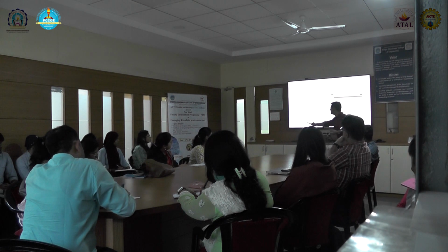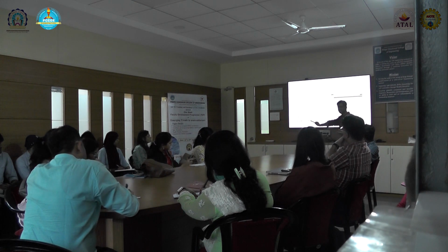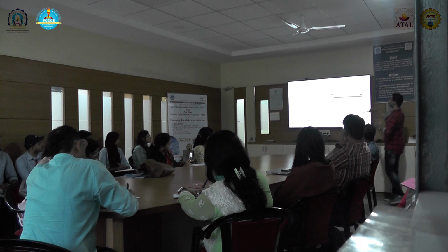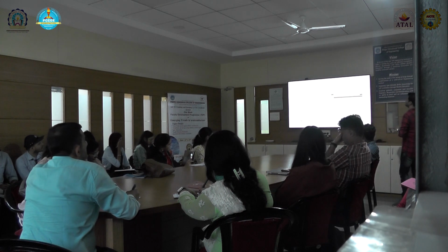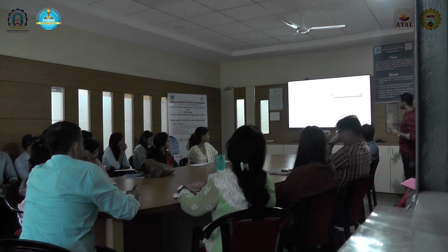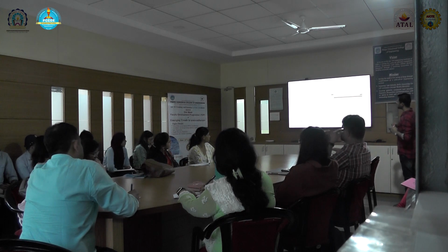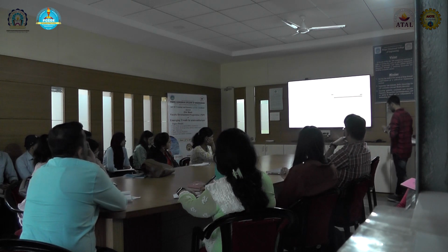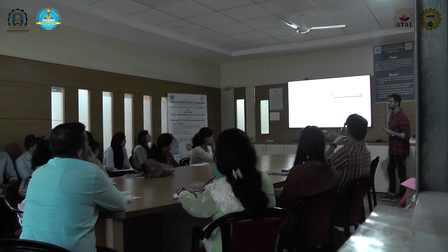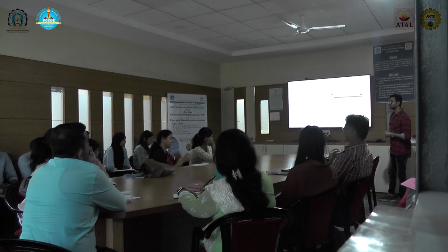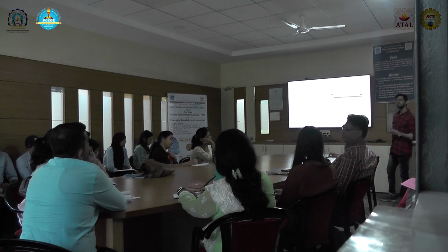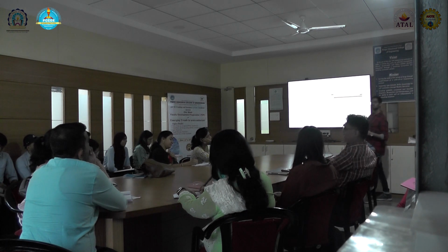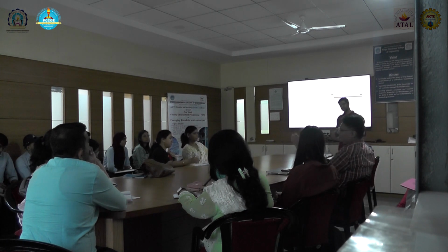If done 1 and done 2 are high in the same cycle, and then when you run formal on this, it will find a scenario where this is getting proven. Cover properties, unlike assertions, don't try to fail. They will try to show you a scenario where these three signals are high. So cover is like, in the simulation world, we write a new test case when full is happening.